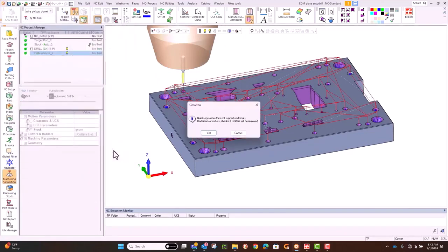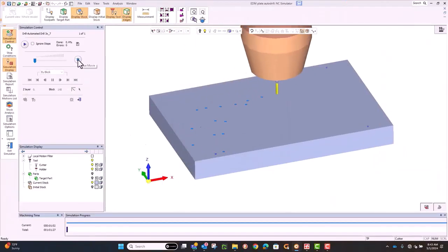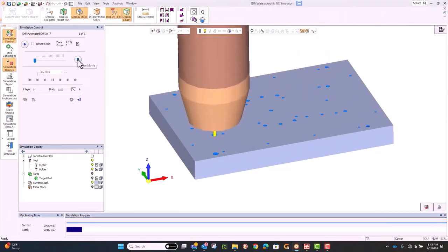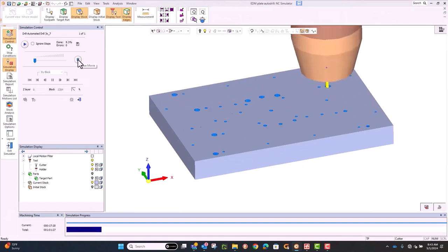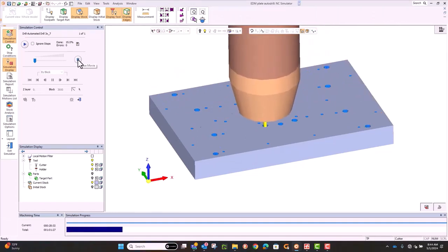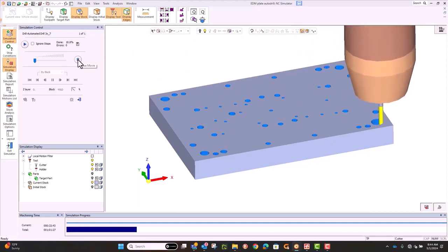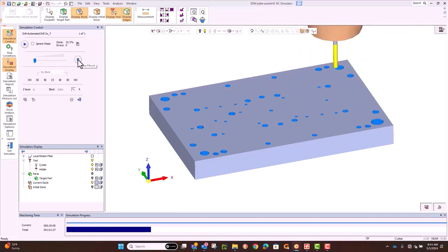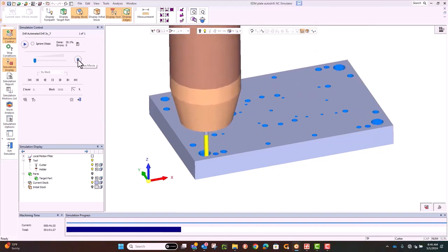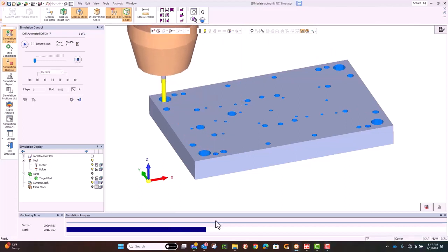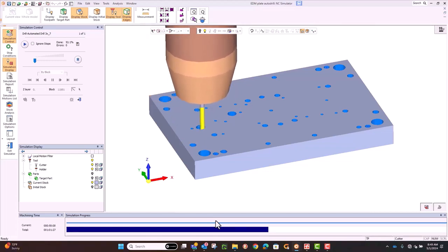Once it's been calculated, it now goes through and sorts this for me. So it's going to do the center drills in all the locations first, instead of doing a center drill here, then a clear hole, and then a through hole. Or if it's, in this case, a counterbore hole, it'll come through and put those counterbores in with a circle mill routine, like you see here, working its way down. It has the capability of doing every type of hole: threaded holes, counterbore, chamfered holes, backward holes, gun drill holes. All those are available, and it organizes the cutter.